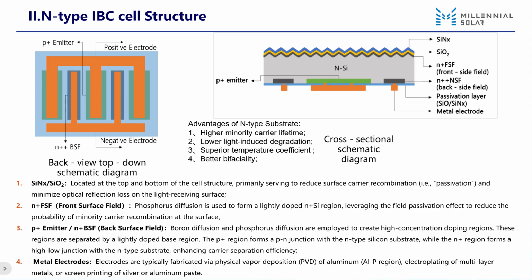Here, the refractive index of silicon nitride is variable, marked as X. We can control the refractive index by adjusting the flow ratio of silane and ammonia. If we want to increase the refractive index, we reduce the ammonia flow. If we want to decrease it, we increase the ammonia flow. So, what's the purpose of controlling the refractive index? Firstly, high refractive index silicon nitride can bond with more hydrogen atoms. More hydrogen atoms mean more free hydrogen, which is useful for bulk passivation. Secondly, low refractive index silicon nitride has an advantage in anti-reflection, which can enhance the optical anti-reflection effect.